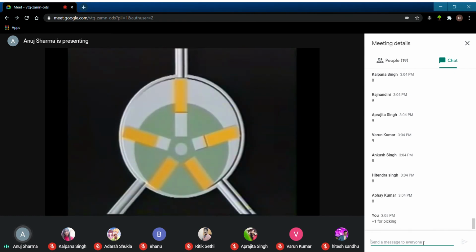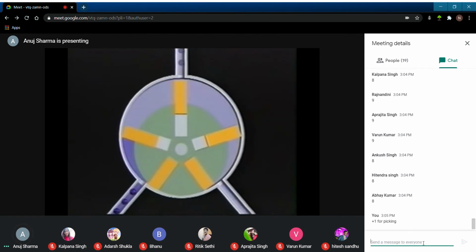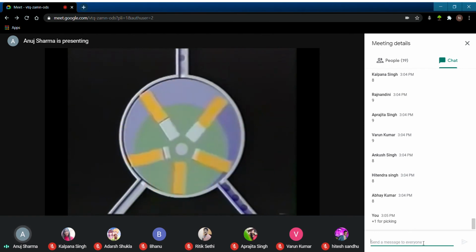The vane motor works by means of a rotor located off-center in a cylindrical chamber. Movable vanes located in rotor slots are forced outward against the chamber walls, sealing the individual chambers. Air enters the smallest chamber, turning the rotor as it expands with the increase in chamber size. The air is then exhausted when the chamber reaches its maximum size. Rotating vane cylinders are available in right, left, or switchable rotating versions.